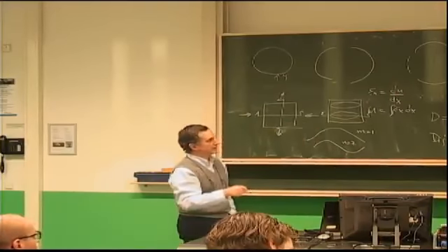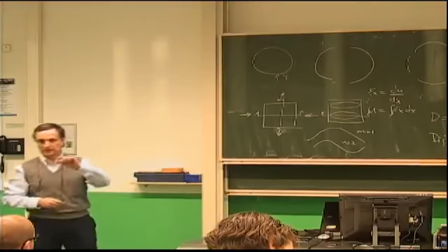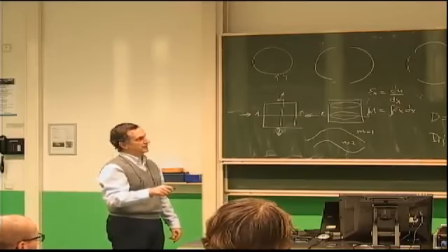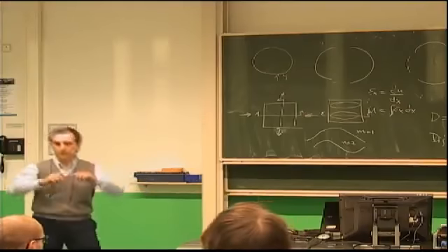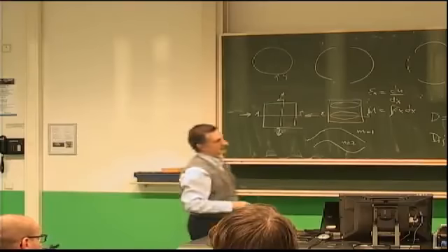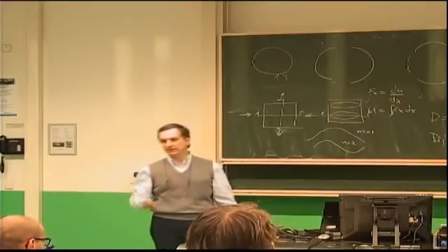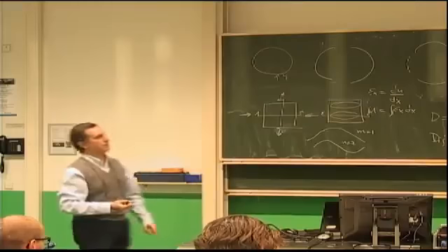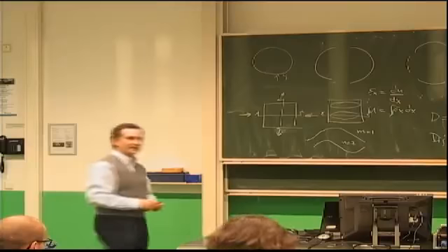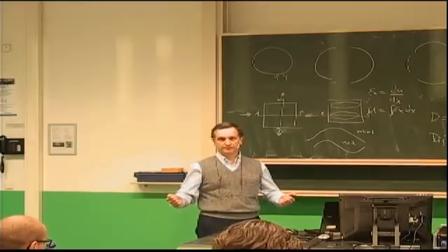We did this very roughly, and in reality the composite material comes in distinct ply thickness. You cannot get any ply thickness you want, which means when you find this 6.3% increase in thickness, most likely you have to round up to the next ply because it will not correspond exactly to a certain number of ply thicknesses. So that increases your weight. And then if you were to include issues like the effect of damage and the environment, which you will be doing as part of your homework, then that gets diluted from 38% weight improvement to something significantly less, which will be much more realistic. Any questions? See you Monday.